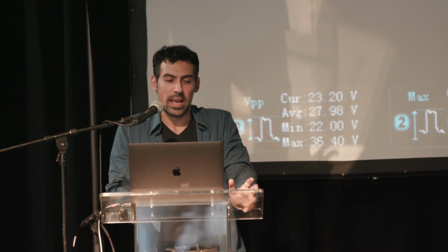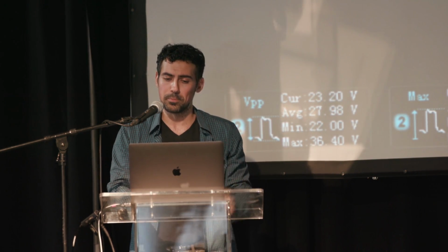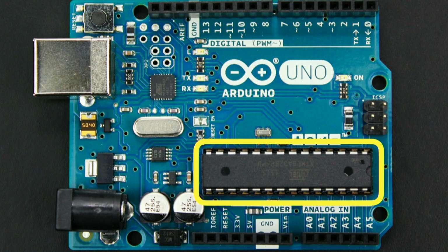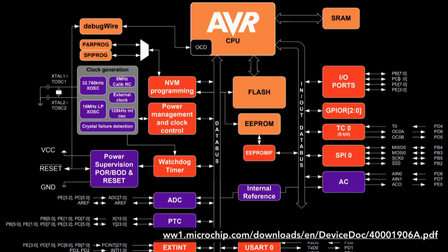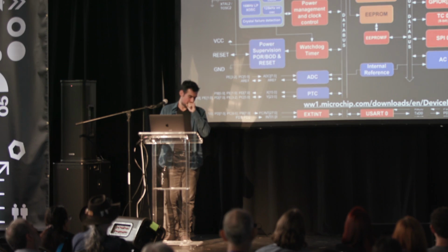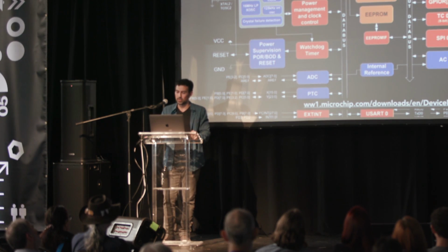And time. Time is an excellent side channel. So we'll use that as a simple example. Again, we'll look at the Arduino Uno. We're all familiar with the Arduino Uno for the most part. Really, the brains of the Uno is the ATmega328P, a standard microcontroller with AVR architecture. We'll take a deeper look here, but a clock is pretty much driving everything on most processors and microcontrollers. So you have a ton of sequential logic that's controlling flip-flops, flash, RAM, FIFOs, all this stuff.